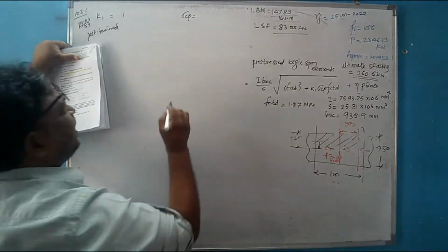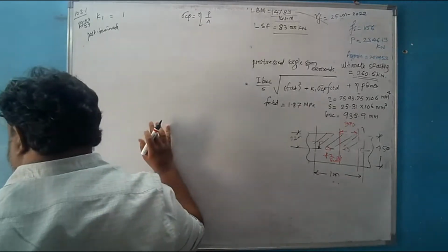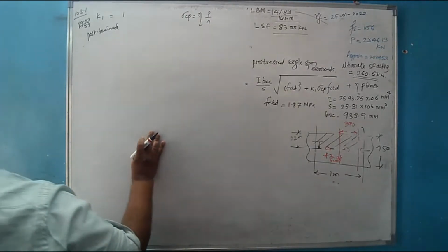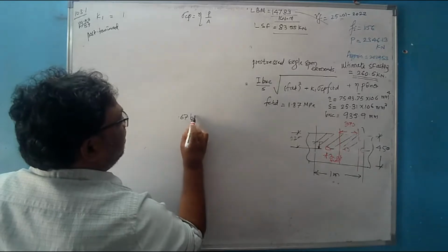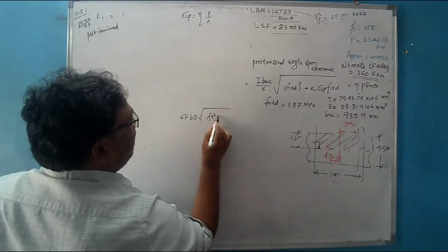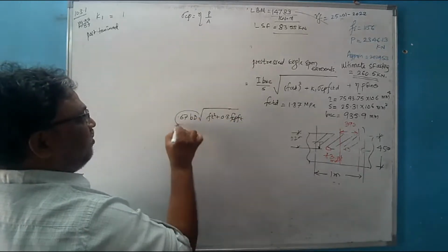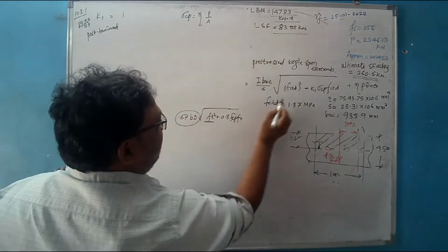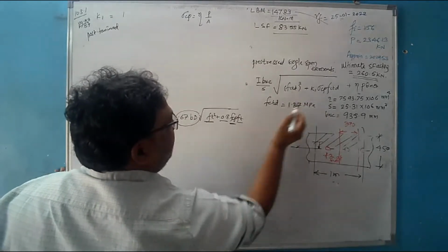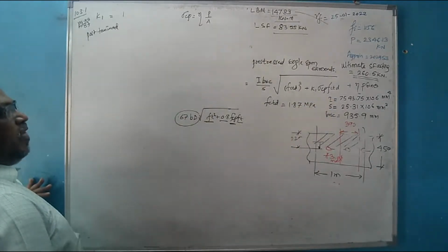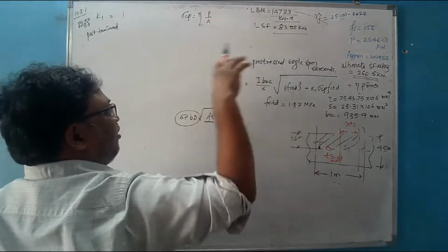Okay, fine. What will this be? It is eta P by A. That's all, the axial compressive stress which is acting. As I said earlier, this equation is analogous to that equation, 0.67 b d under root of f_t squared plus 0.8 f_cp f_t. The 0.67 b d is this part, f_t is this part, 0.8 is this factor, f_cp is this sigma cp. So f_cp is eta P by A, the same thing here. Sigma cp is nothing but eta P by A, the axial compressive stress.